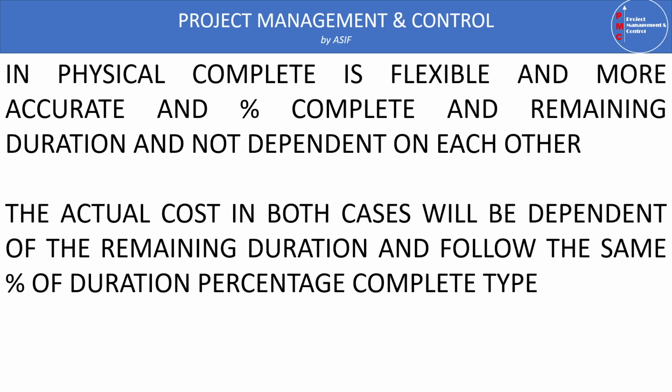And in fact, in earned value management, the actual cost is the cost which is incurred. This actual cost which is incurred cannot be known by the system till you tell the system what the cost was, or how much you spent. So in almost all cases, it is not recommended to let P6 compute actual cost.